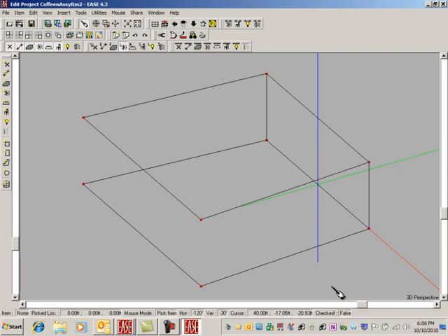So, we could create a little surface here that's below the stage, the apron of the stage, but we don't want this wall here because we're going to carve this up. So we could get rid of the face, just delete it, but where it is stays there because we have the roof added. Now notice this line went away down here. We'll make that in a minute.